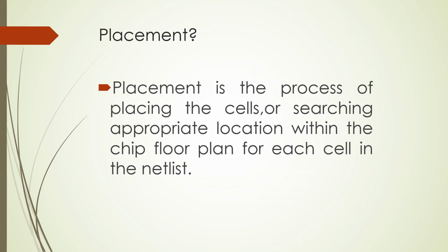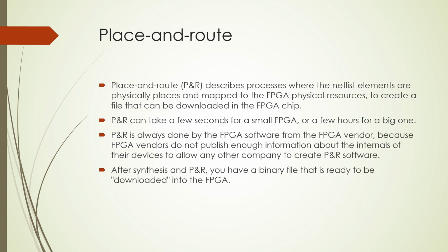So what is placement? Placement is the process of placing the cells, or searching the appropriate location within the chip floor for each cell in the netlist. Place and route describes the processes where the netlist elements are physically placed and mapped to the FPGA physical resources.